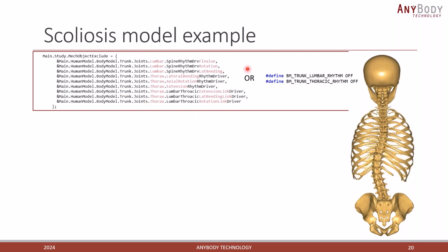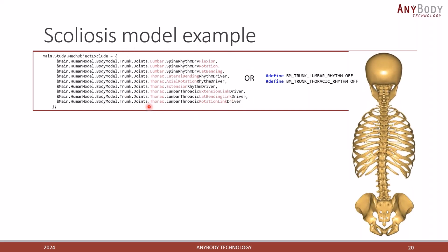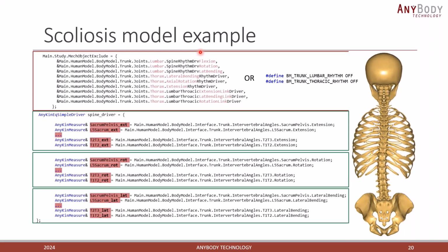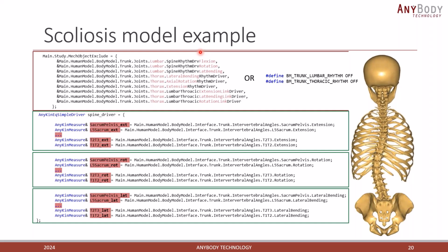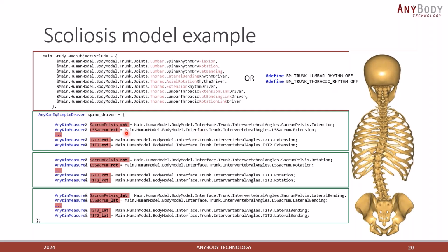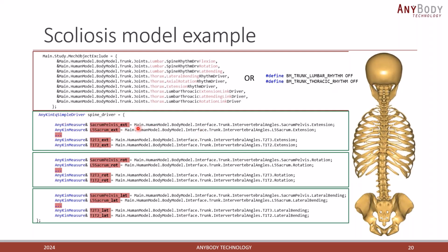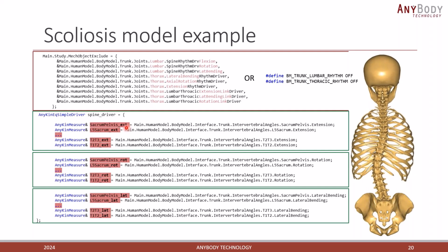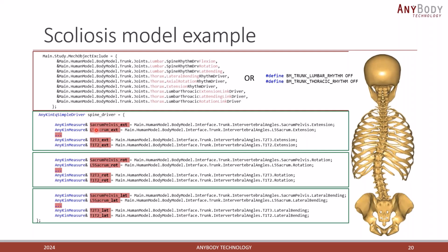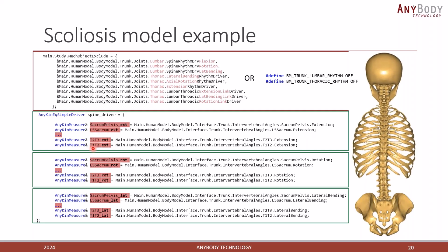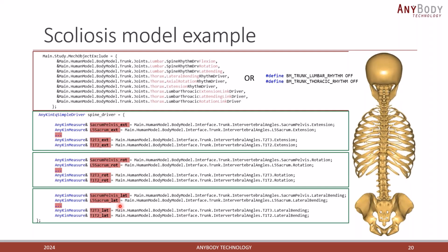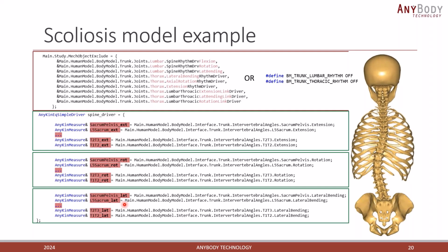But I just wanted to show you what the rhythms are. When you exclude those, you have to add some drivers to drive the spine, and then you can just take a simple driver and take the measures, like the extension measures of sacrum, pelvis, L5, sacrum, all the way up to T1, T2, and then do it for axial rotation and lateral bending.